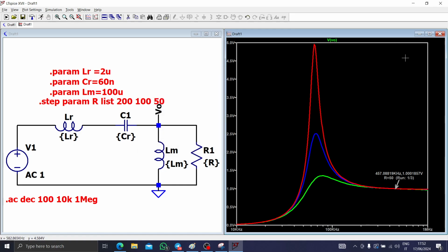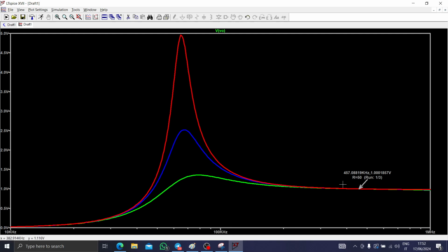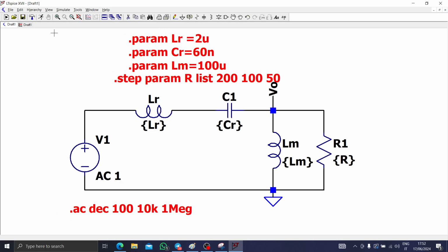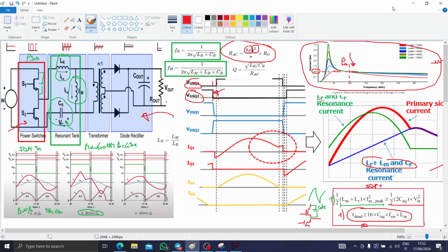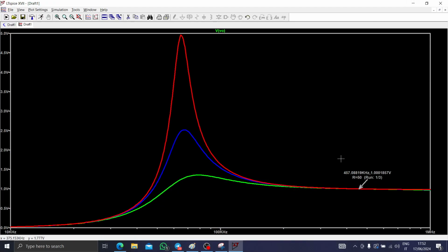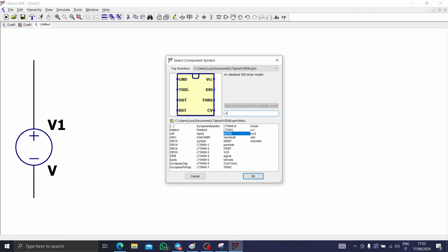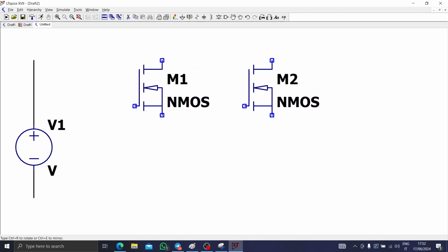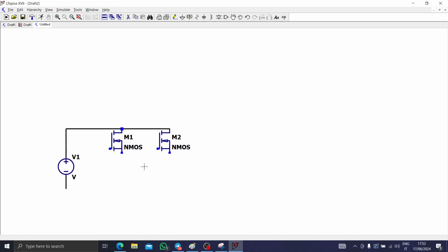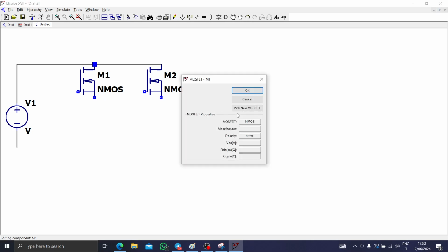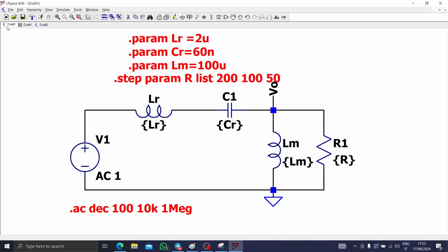Okay, as I said at the beginning of the video, I will be designing the frequency at 450 kilohertz, and as you can see in my calculation, more or less it turns out right. We have 450 kilohertz as F0, so we can set the switching frequency to 400 kilohertz, and we are free to go. So let's perform the real simulation this time, and let's put the MOSFET because we need the full bridge configuration. Okay, so here we have to be careful because we need the gate voltage from the primary and also for the secondary. So the MOSFET will be the first of the list. Let's import the tank.